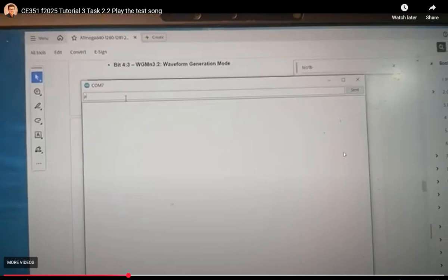And I actually typed something in the serial monitor, because the serial monitor is UART. It has RX and TX, right? So when I type something over here and press enter, it's actually sending that byte, or ASCII code, through the USB to the board. So you have to program something on the board to be ready to accept anything being sent to the microcontroller. If I type something and press enter, it sends it, the board receives it, and then provides a certain response from the microcontroller. It's actually sending things back through the USB to the serial monitor. That part is pretty simple. It's already given to you, so don't worry about that part too much.